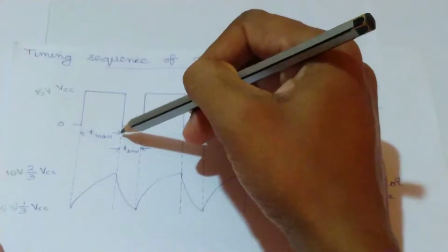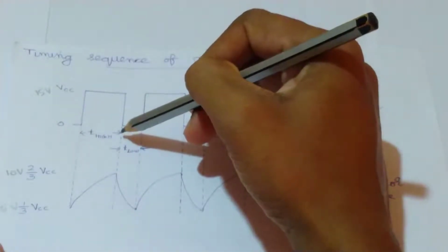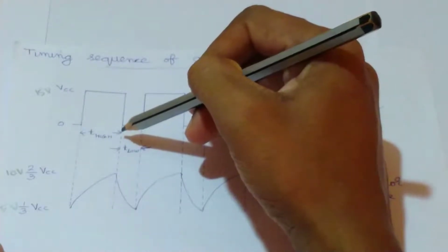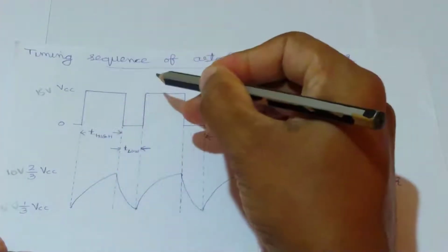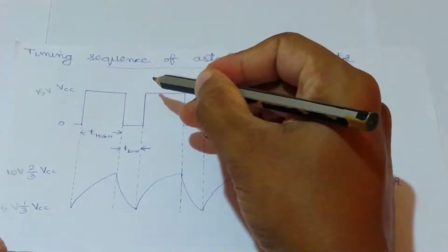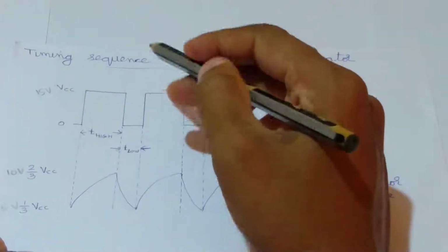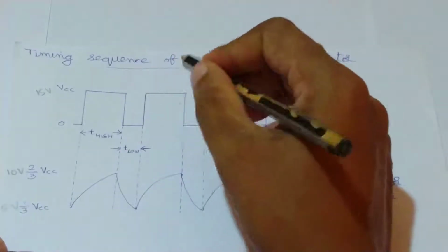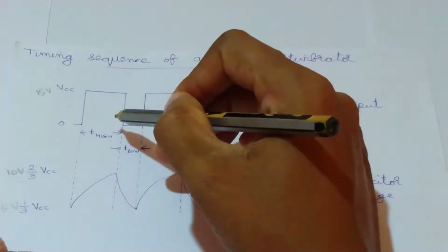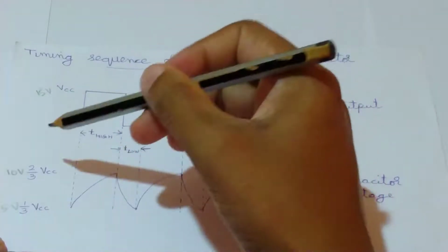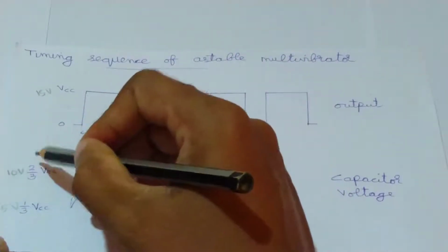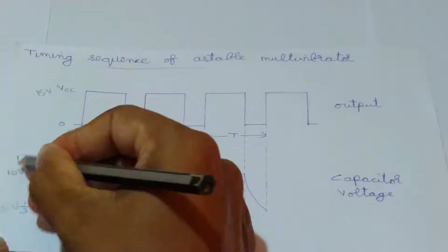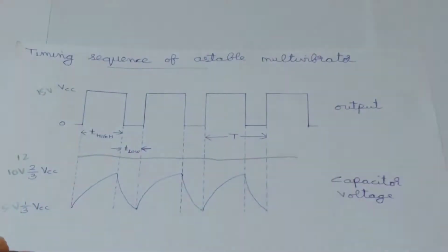Then in the case of pulse position modulator circuit, to that fifth pin the modulating input signal is applied, and then consider that modulating input signal is increasing in positive direction, and consider the instant at which the voltage at the fifth pin is 2 volt. Okay, when 2 volt appears at the fifth pin, then at the inverting terminal of the upper comparator, now the voltage is 10 plus 2, 12 volt. Okay, and that is greater than this 10, so consider this is that point.